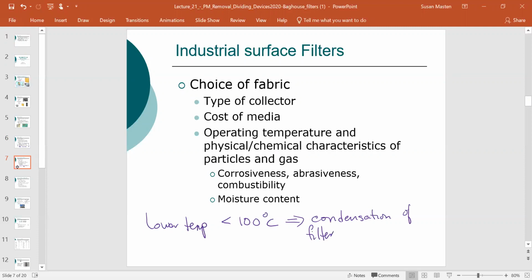Now remember, think back at what we've talked about, for instance, with acid rain. You have SO2, you have water. What do you produce? Sulfuric acid. We have NOx, we have water. Potentially, what can we produce? Nitric acid. So the problem is that if we have water, we have the potential for corrosion, and then degradation of your filter.